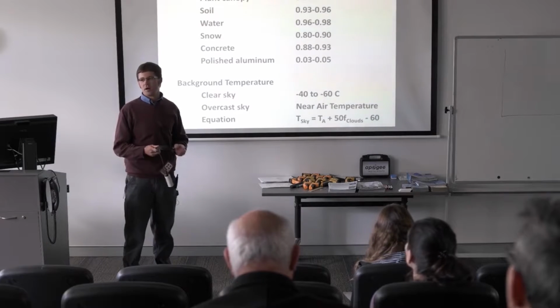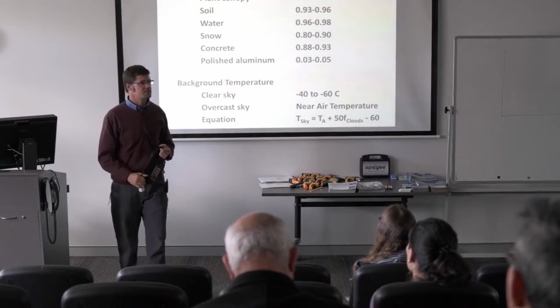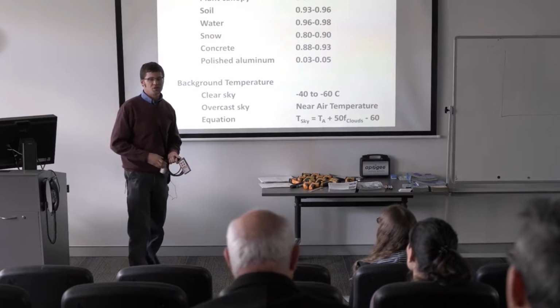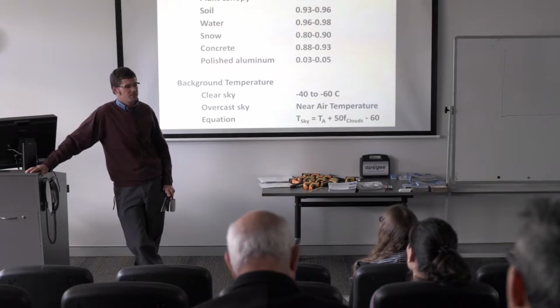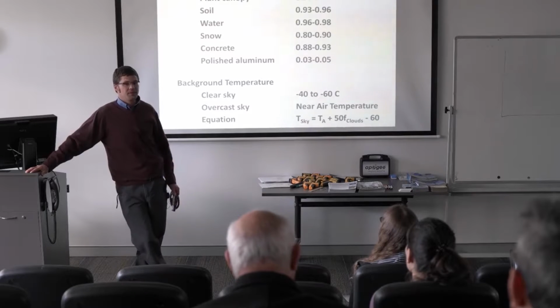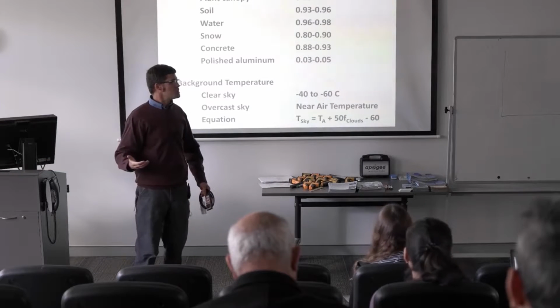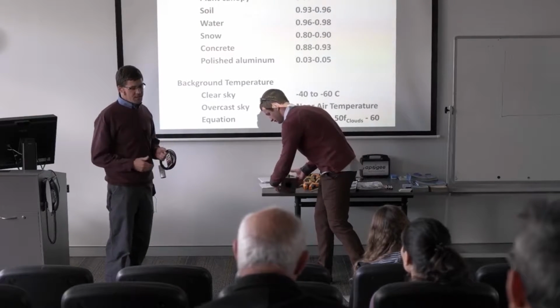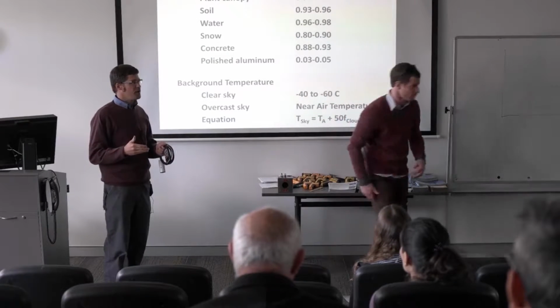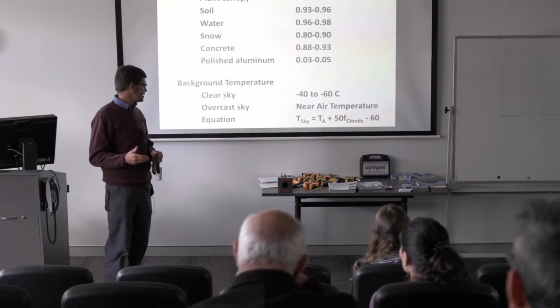So let's just assume the water temperature will be 50 or 60 Celsius. So what should the black body cone surface temperature be? What's that? Yeah. It should be close to the true temperature because it's a black body, meaning it's emitting the maximum amount of radiation it should emit for that temperature.